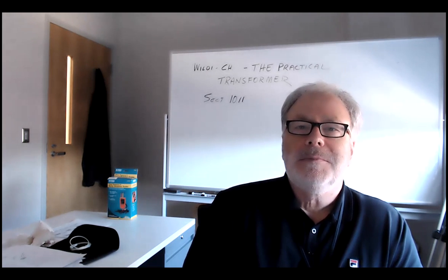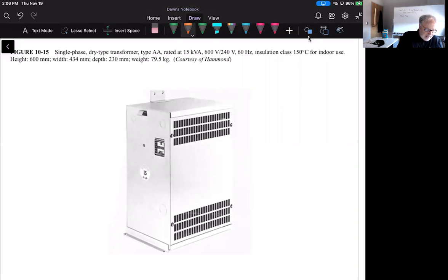So we're told in this section that indoor transformers, and again, think about all the different considerations that have to be made for these electrical machines, right? And where they operate, the operating environment, is one of the primary ones. And so here we're specifically talking about indoor transformers that are less than 200 kVA on their rating. And so they can be naturally cooled by natural flow of surrounding air.